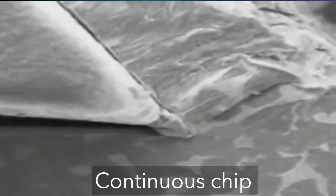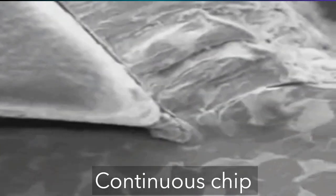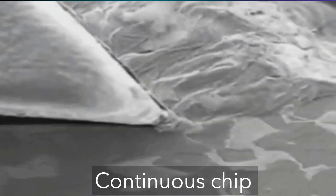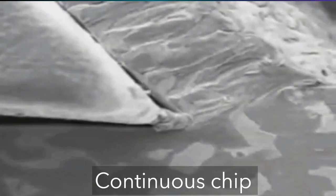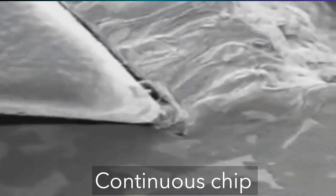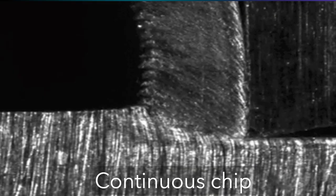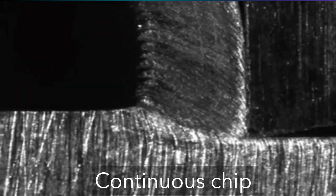Long, continuous chips, as in turning, can cause problems with regard to chip disposal and tangling about the tool. To solve these problems, turning tools are often equipped with chip breakers.